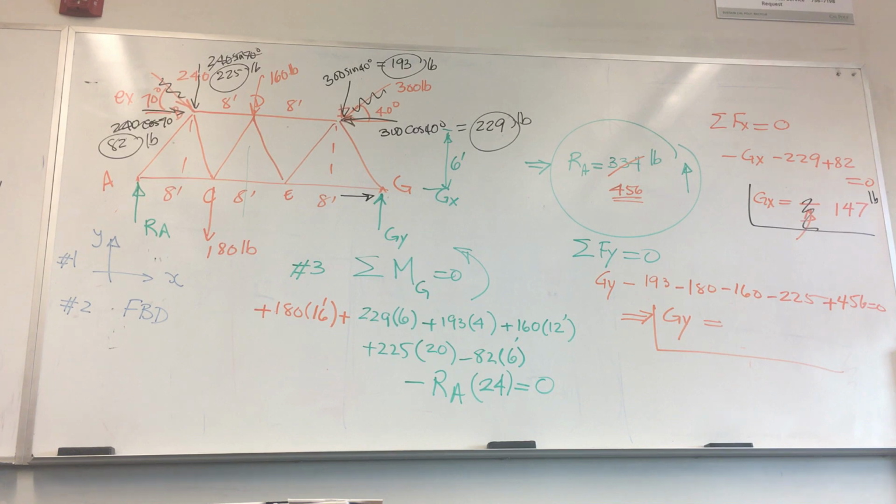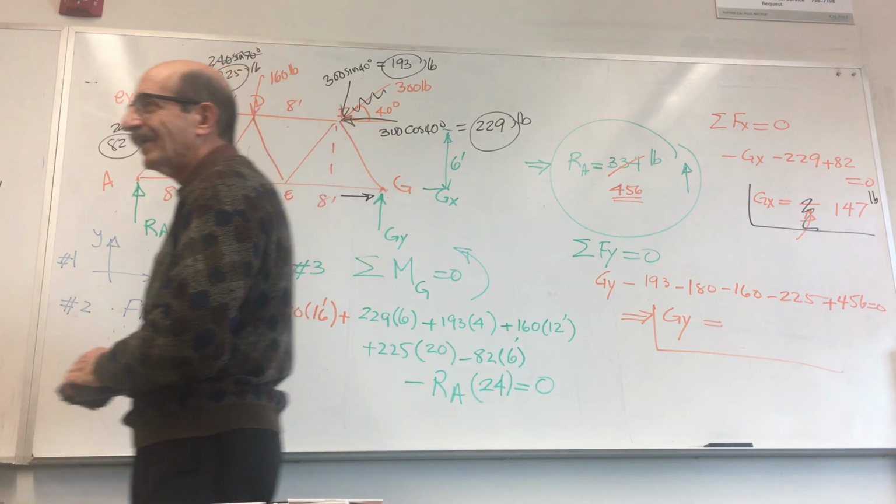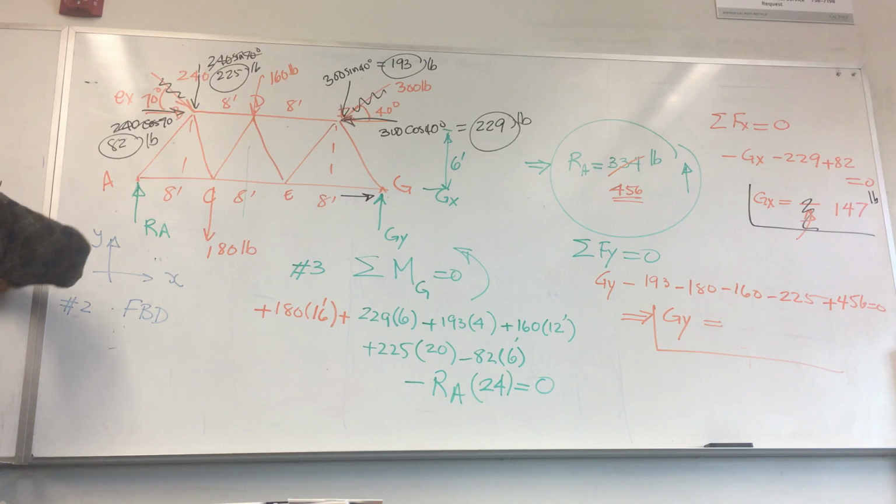The part that I want to know how to do was how to find the intersection of the line of action. Yeah, it's the type of problem we did, you know, you need to move the forces to a point that you don't know where it is, X, say from A, right? Then, since the summation of all the moments has to be 0, you take summation of moments about that point, you find X. You remember we did a problem like that?